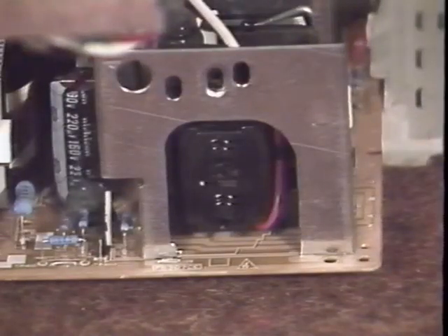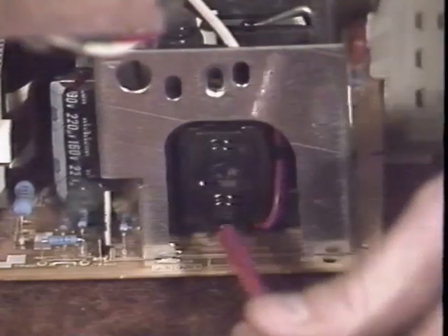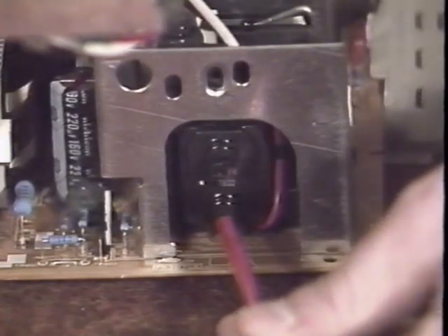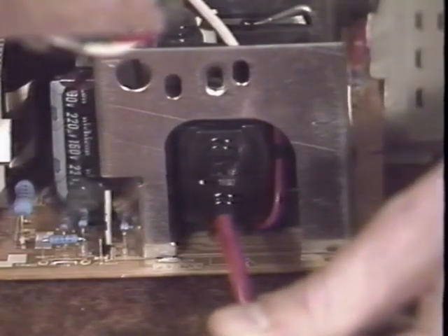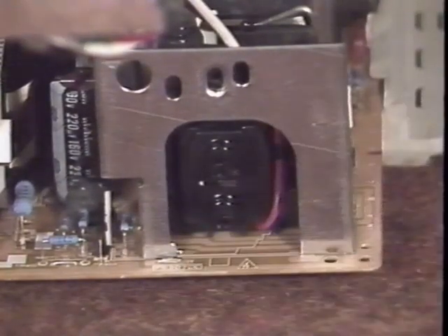Mark the position of the screen control, which is often mounted on the flyback transformer, and turn it down until the screen is black. Then turn it back up until a very faint trace appears. Once the red trace is as dim as possible, turn the green bias control up until the red trace becomes a dim yellow. Then turn up the blue bias until the trace becomes a dim white or gray.